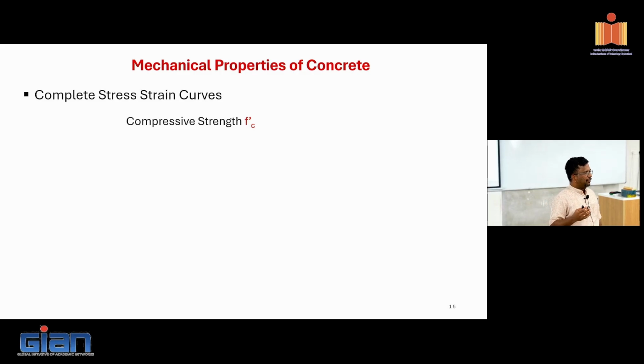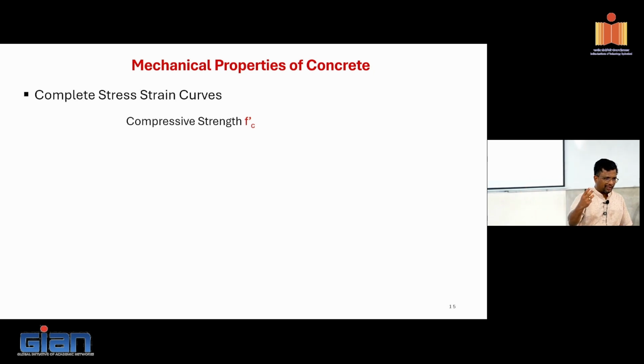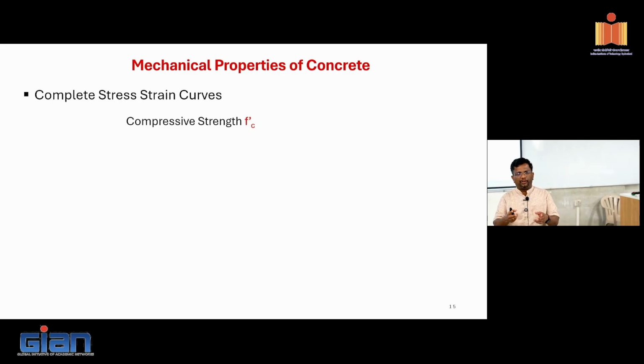You do design for a precast pre-stress system. How many stages of checks do we do in a pre-stress precast system? In reinforced concrete we do it at 2 stages, right? We design for ultimate conditions and then we check for serviceability. These are the 2 main limit states. But in pre-stress, what is the extra thing we need to do? It is also during the transfer of pre-stress, right? So 3 stages we need to check.